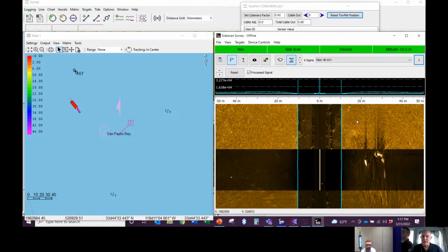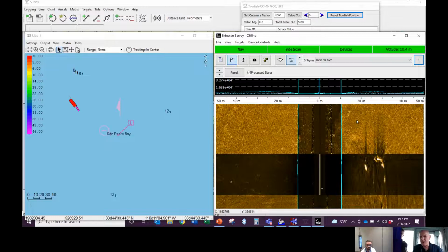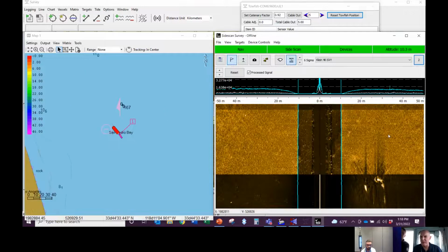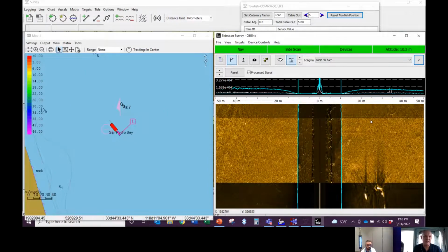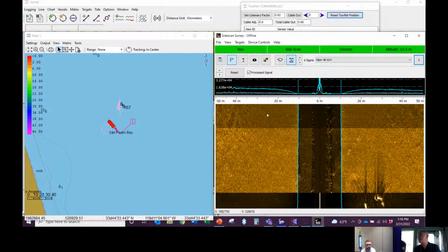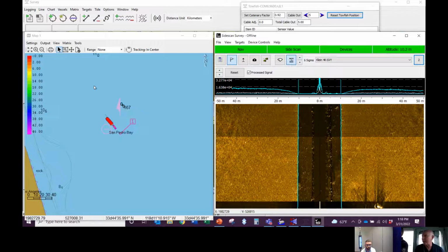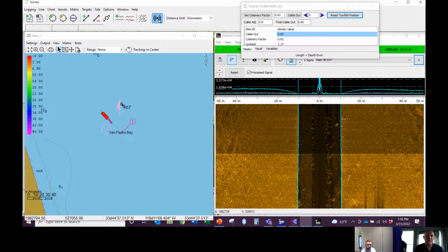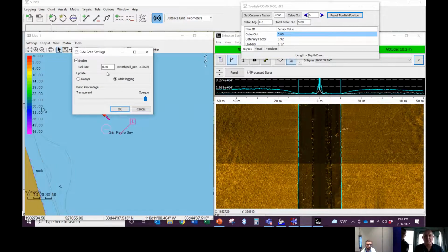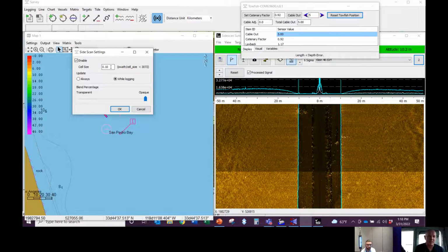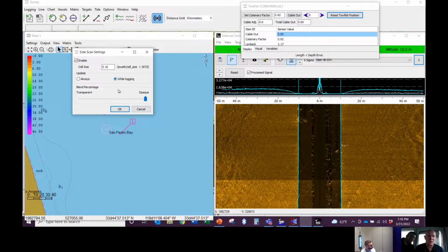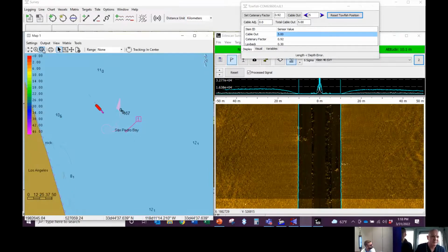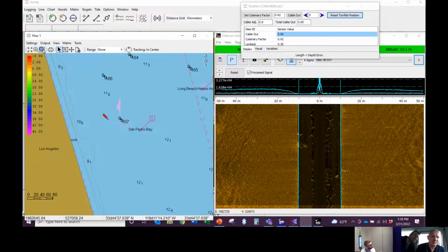Right. When you're doing a real-time mosaic, whatever frequency you have selected here in the first window is the frequency that will be mosaicked. So we are going to use the 600 kilohertz to mosaic it. If I can ask Chris to come up towards line 1, we can start the real-time mosaicing. Now it's as simple as going to this little button here, setting up the size of your real-time mosaic, and we're going to do a 10 centimeter real-time mosaic, and we're going to collect this while we're logging. So as we approach the start of the first line, we're getting up to it.